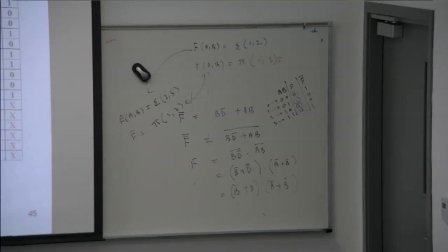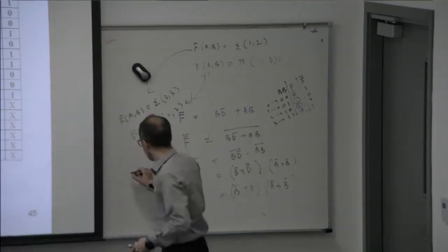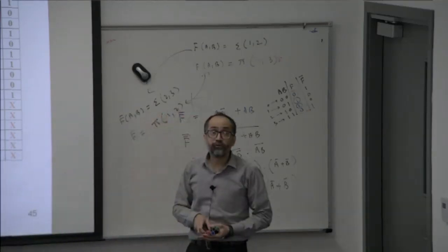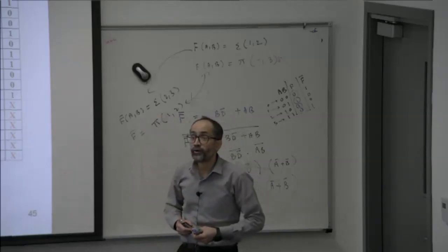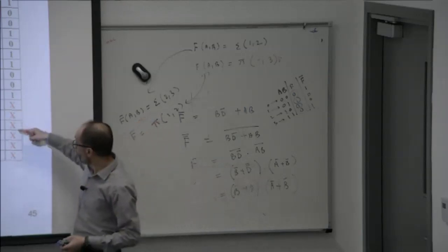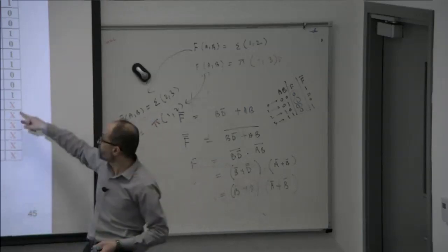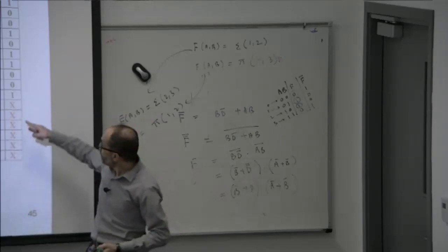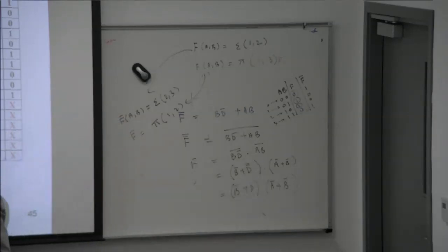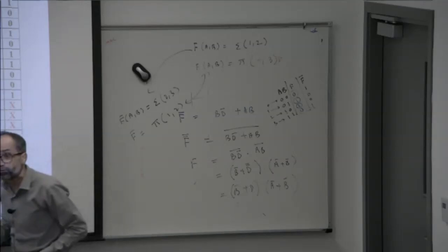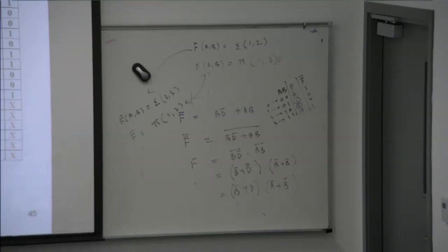So now assume that we are working with digital codes, BCD codes. We have BCD digits. What is the valid value of any BCD digit, from 0 to where? 9. Are these valid codes or invalid codes? Valid codes. But 10 to 15 are invalid codes. These are called the don't care condition for BCD. Will all these entries be don't care for hexadecimal? No. This will not be a don't care for hexadecimal, but it's a don't care for BCD. Why in BCD? Because BCD ranges from 0 to 9. This is called the don't care condition.